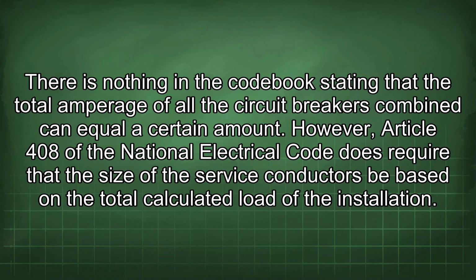There is nothing in the codebook stating that the total amperage of all the circuit breakers combined can equal a certain amount. However, Article 408 of the National Electrical Code does require that the size of the service conductors be based on the total calculated load of the installation.